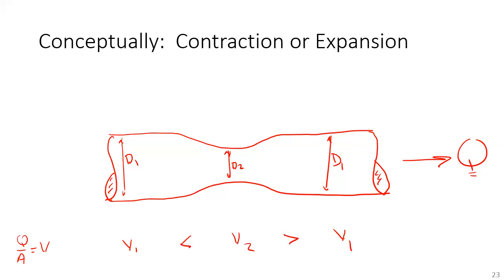Everybody agree? So let's say that we put a manometer here. And the fluid level in the manometer is here. And so at that first location where we have the manometer, we have some pressure P1, and as a pressure head, we would divide by the specific weight of the fluid.